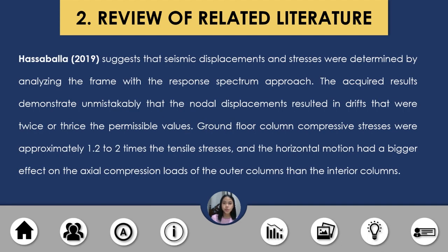Ashabala, published in 2019, suggests that seismic displacement and stresses were determined by analyzing the frame with the response spectrum approach. The acquired results demonstrate unmistakably that the nodal displacements result in drifts that were twice or thrice the permissible values.